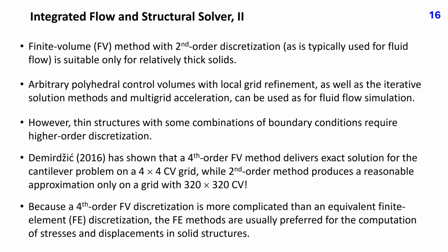Finite volume method with second-order discretization, as is typically used for fluid flow computation, is suitable only for relatively fixed solids. Arbitrary polyhedral control volumes with local grid refinement, as well as the iterative solution methods and multigrid acceleration, can then be used as for the fluid flow simulation. However, thin structures with some combination of boundary conditions require higher-order discretization.